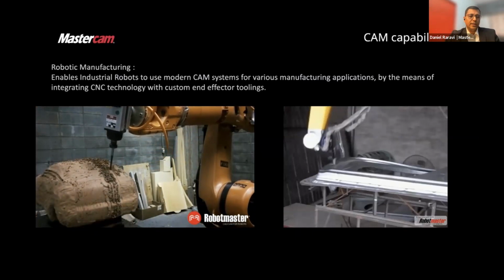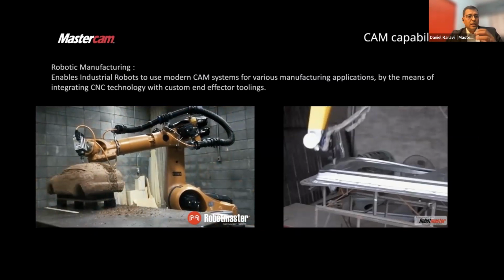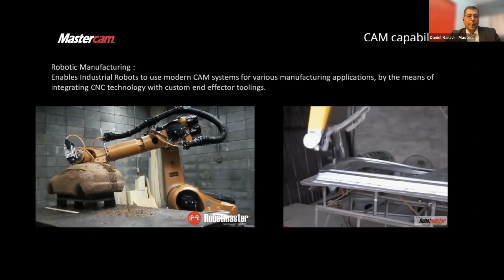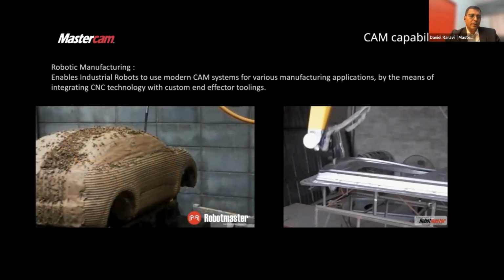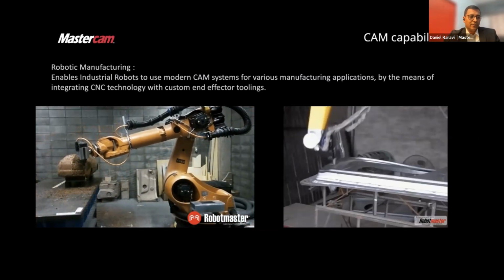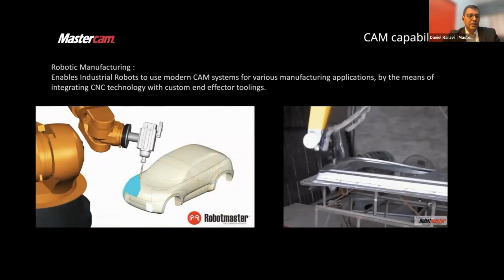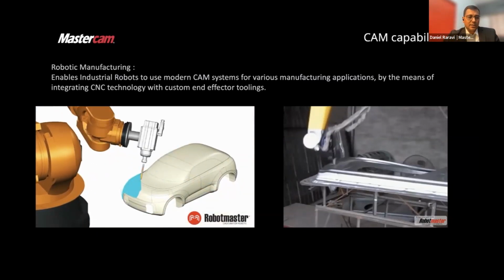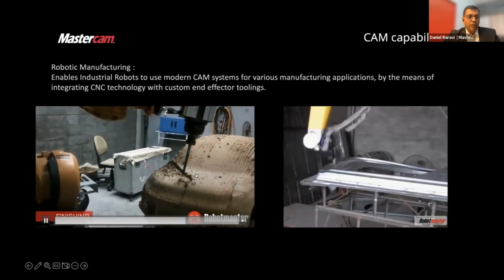But with the help of industrial robots and changing the end tooling to a spindle with a tool mounted on it, we are able to generate and model out the parts within CAD software using surface modeling tools, and then provide the output to CNC controls that is integrated with the parts in order to achieve what we are seeing here now.